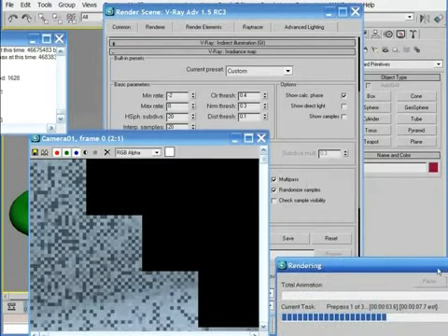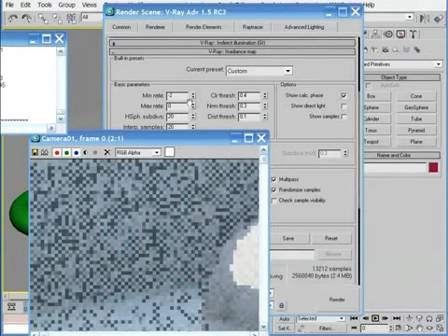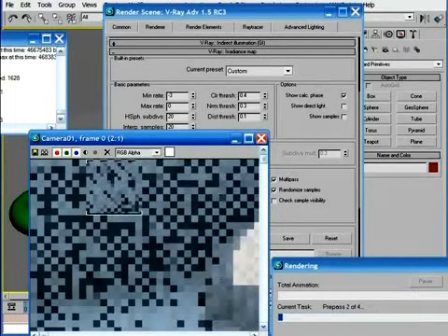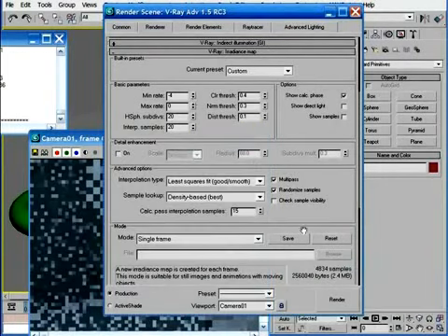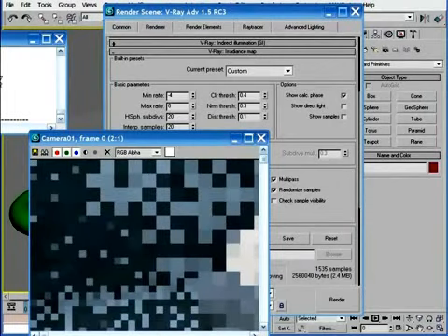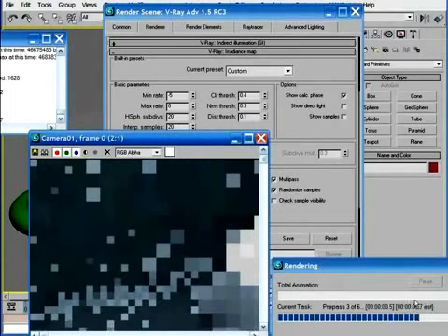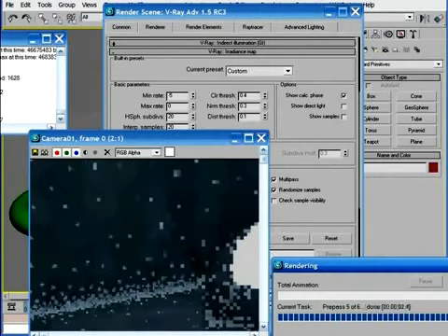I'll set it to -2, and when I render it again, you'll see that the dots that make up each individual bucket are larger. I reduce it again to -3, and the dots again become larger, and the Radiance map resolution is lowered, at least on the first pass, with each successive drop in the minimum rate value. And I can continue to drop it until the quality of the Radiance map on the first pass is ridiculously